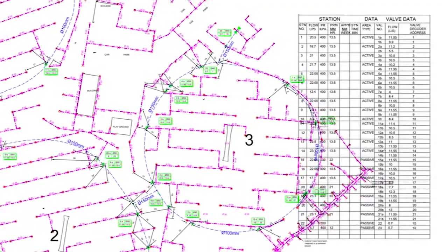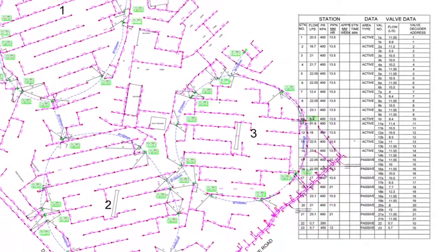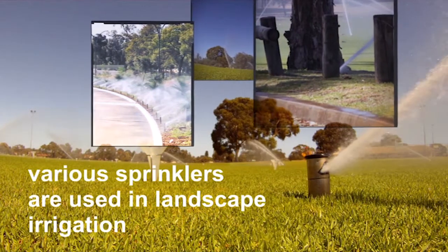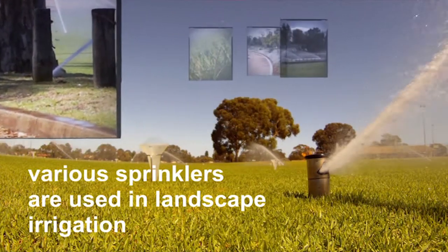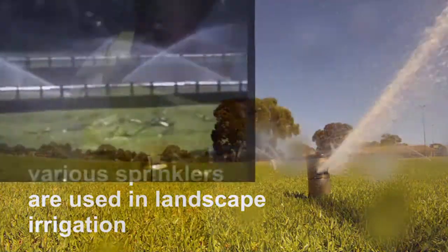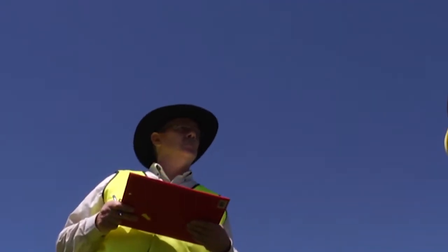A system layout plan is not always available, but the provision of an as-constructed drawing should be a requirement for any new system. There are a wide range of sprinklers available for use in turf irrigation, and the correct selection of sprinklers for any given area is very important. This selection process is most effectively achieved through consultation between the designer and an experienced manager of the system.